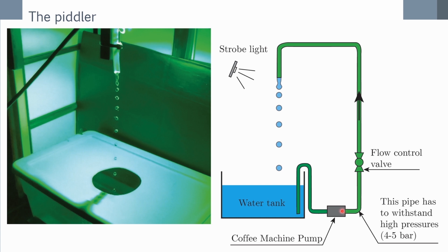So every forward stroke, it will move a slug of fluid forward. But every backward stroke, the check valve is going to shut off, and then you don't get any backwards motion of the fluid that has already made it outside of the pump. And because there's a void now, you actually get suction from the opposite side, and then you keep on doing that, and you get a back and forth motion of the fluid that moves the fluid forward in slugs